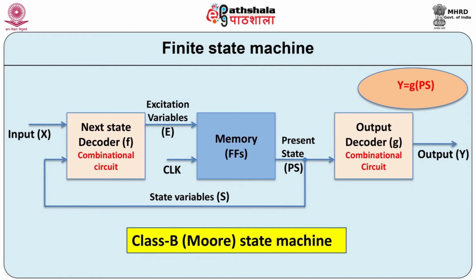Both Mealy and Moore machines are widely used. In some cases, it is not possible to get the circuit that are combination of both. That is, some outputs depend on both inputs and present state of the state machine. Other outputs depend on present state of the state machine.